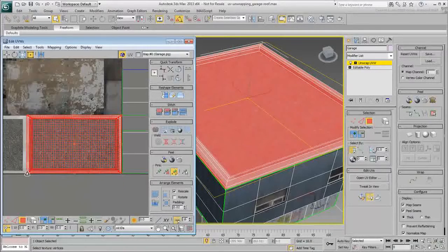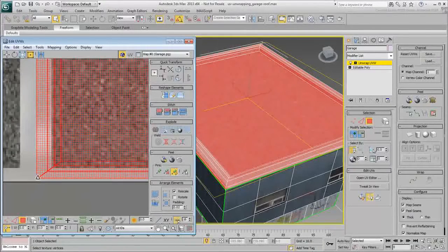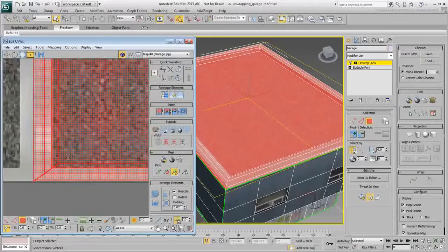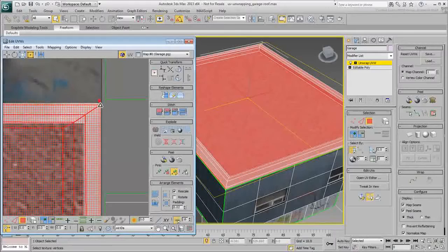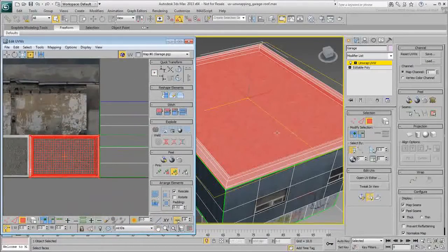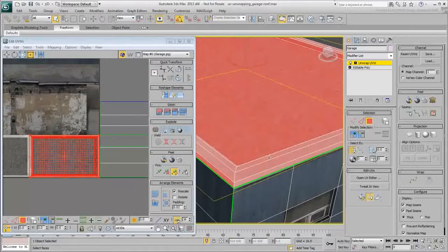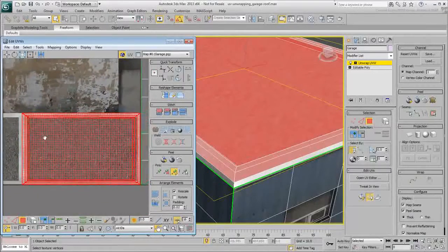The lip around the edge is running parallel to the projection. It probably won't show much distortion because of the nature of the white pixels, but let's be thorough just the same. With the roof polygon selected, click the Shrink button to remove the lip from the selection. Now scale the cluster to a center point by using Ctrl-Alt.